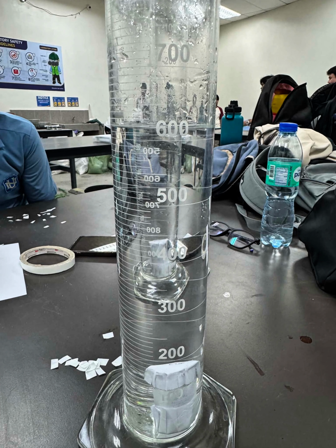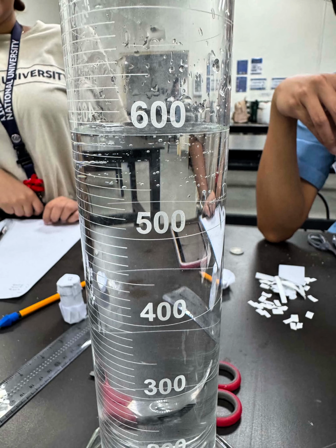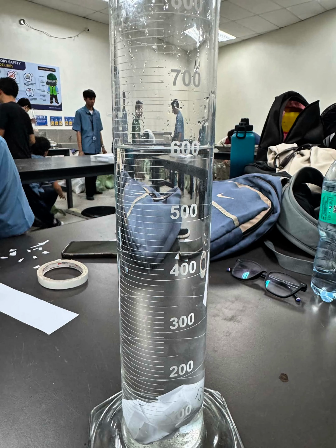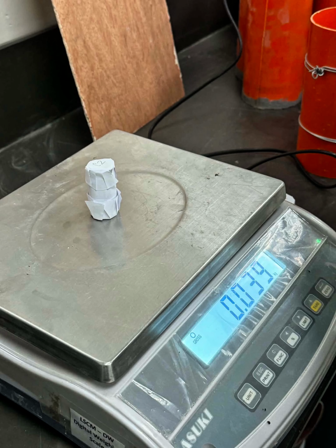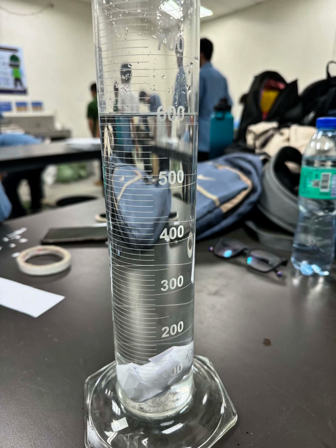In conclusion, the experiment successfully demonstrated the determination of density and unit weight of fine and coarse aggregates using proper laboratory procedures. The water displacement method provided an accurate way of measuring the volume of fine aggregates, while the rodding and leveling method ensured consistent measurement for coarse aggregates. The computed densities and unit weights are essential in construction material estimation and concrete mix design.